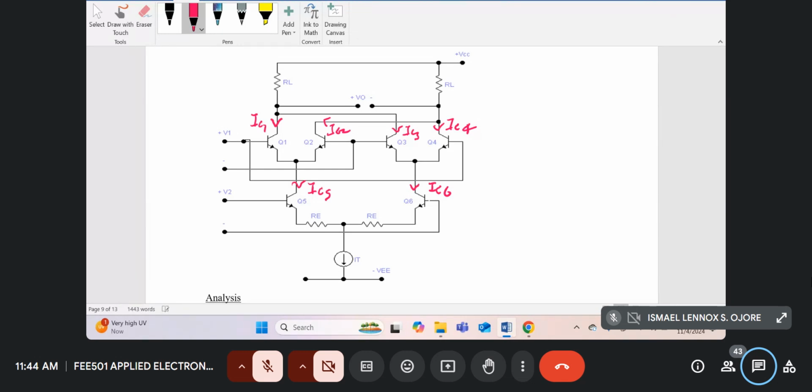Which ride on top of the quiescent. So I said, for example, if IC1, when there's no signal, is 2 milliamps, and I put a voltage V1, and it changes from 2 milliamps to 3 milliamps, so they change the delta from the quiescent, there will be 1 milliamp. So that's the current I'm considering. That's the current as a result of the input voltage, not the currents used to bias the system. And I'm using capital letters, even though they're signal currents. So please note that, it may bring confusion.